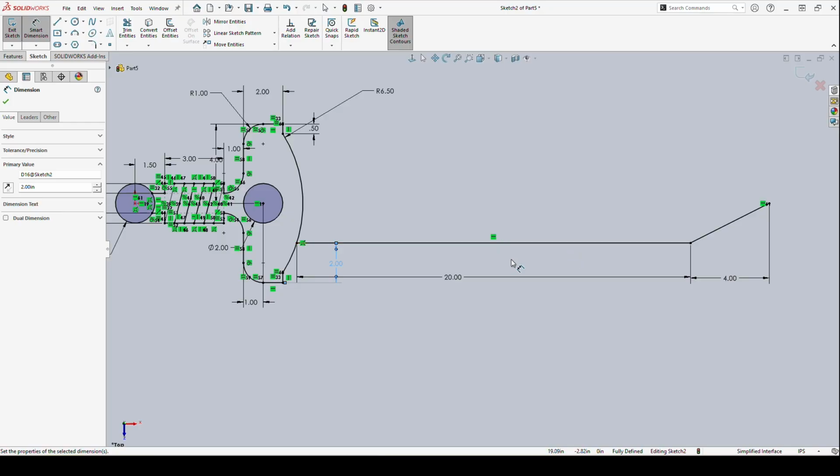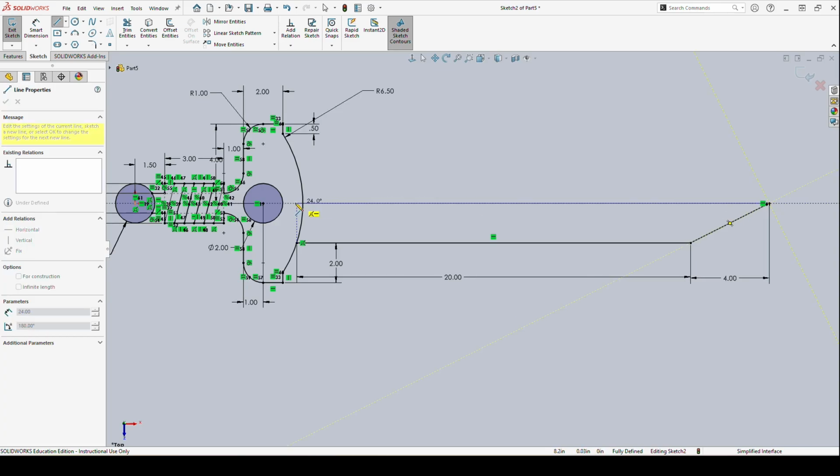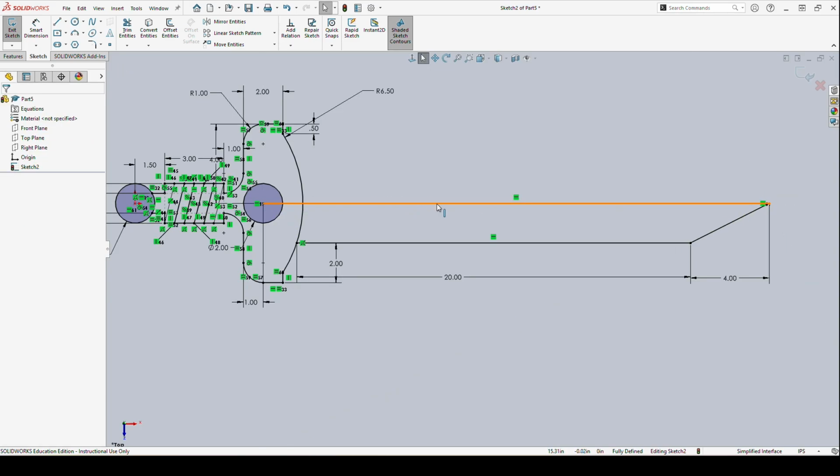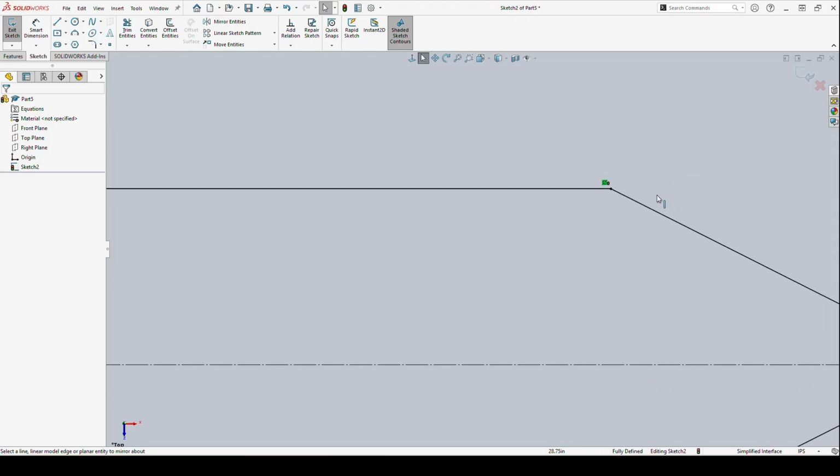But now we're going to talk about a couple of sketch relations that can really only be made automatically. You're very rarely, if even possible, going to see them made by adding afterwards. The first one, we're going to go ahead and use a mirror command, and we create a mirror image of this sword. And unfortunately, zooming in does not actually make the sketch relations any bigger. They try to stay small enough that they're out of the way.